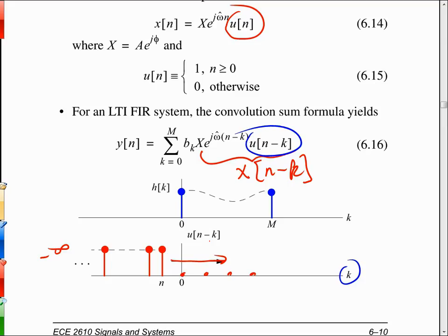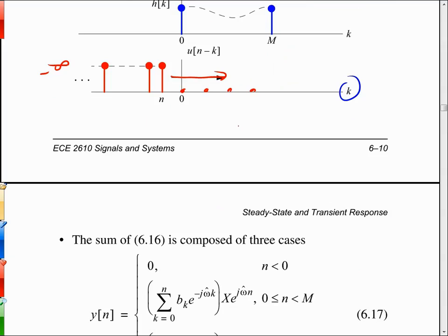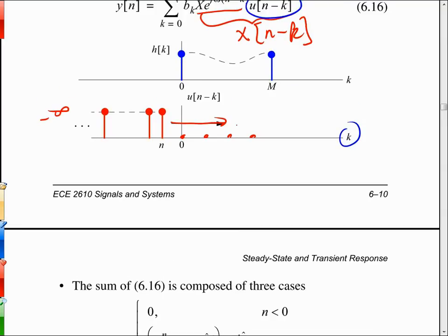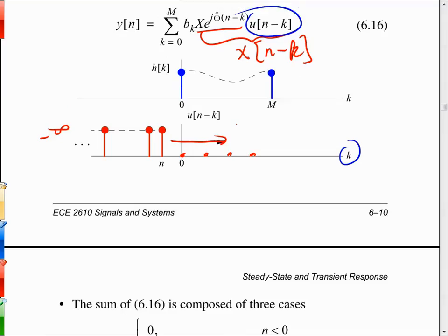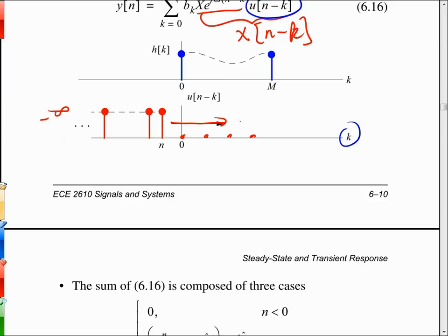So the net effect of that, when we combine that with the complex sinusoid right here, is that when n is less than 0, there's no overlap in our convolution sum. So in our table entry method, we'd have no terms to multiply and sum up. When n is greater than 0, we're going to have a few terms that overlap. And then we can carry this all the way through to when n is greater than or equal to m, we have full overlap. And from thence on, we're entirely, completely engaging the filter's impulse response.